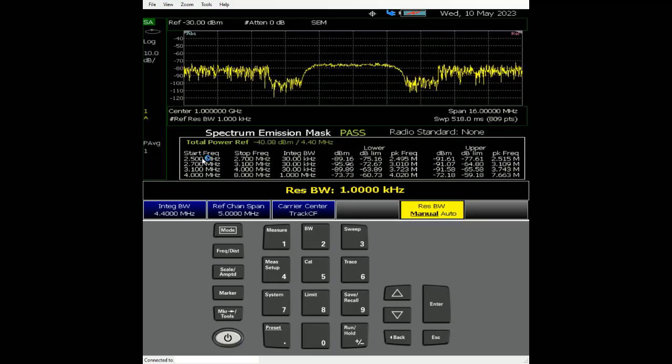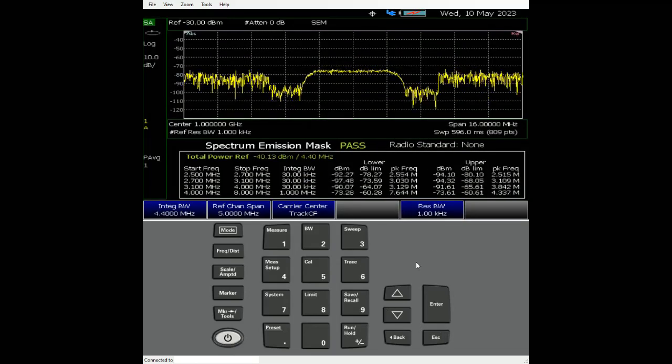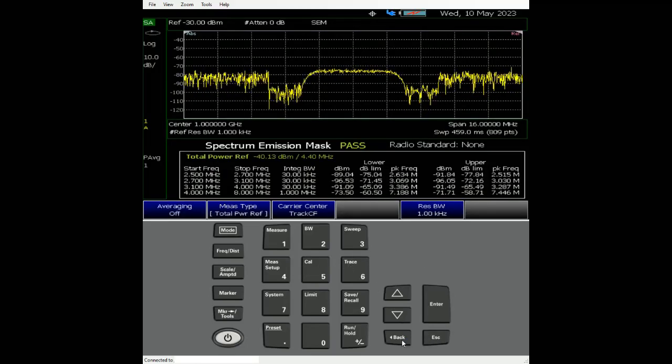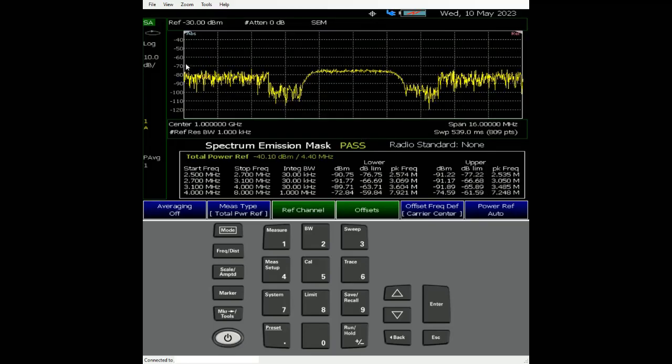When there's an offset closer to the channel measurements, we can change the integrated bandwidth so that you can see the noise floor changes as well. Right, so far so good. Let's go to setting up the offset frequency. What we want to do is get an absolute line down, and then a flat line on top. So it's pretty much like what you've seen in the beginning.